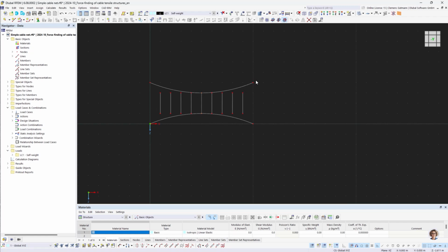And I want to connect those straight lines now to the arches, and there's a quite handy way to do this. There's an option that has not been available in the software for too long, and that is the extend graphically command. There's the opposite command as well, trim graphically. It does the same, but the other way around.